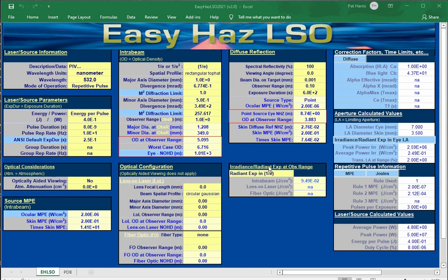We illuminate the particles twice within a few microseconds. We take the image of the first illumination and the second illumination. We're able to compare the particles' positions such that we can get the distance the particle has traveled. We know the time between the two images, and we can calculate the velocity of the fluid. It's a lot easier said than done.